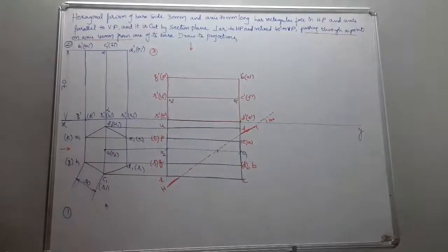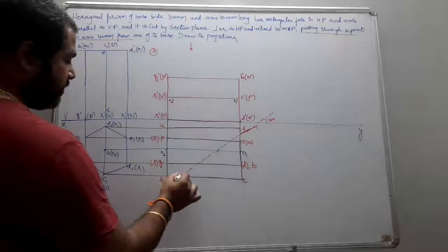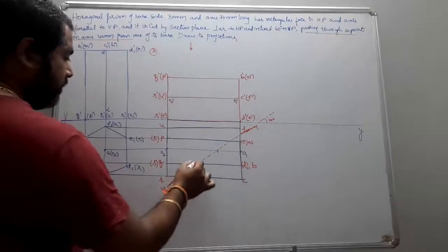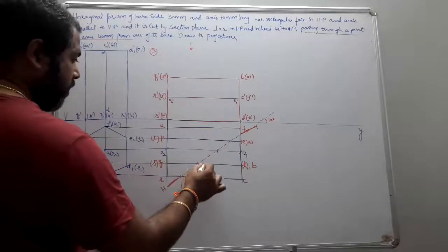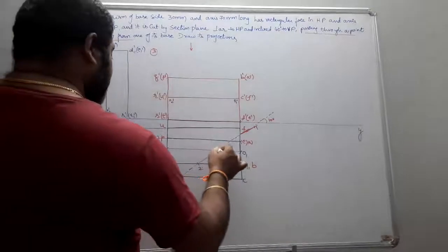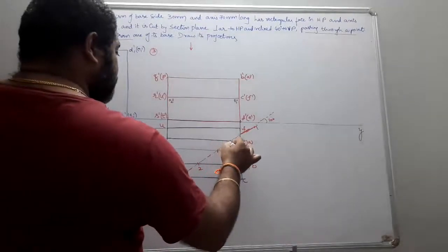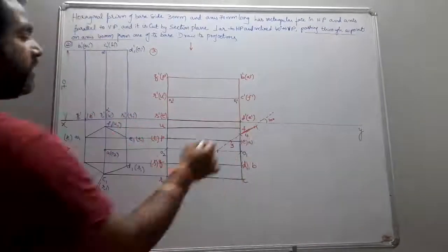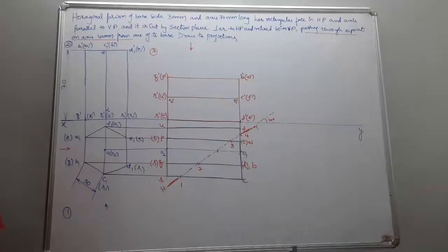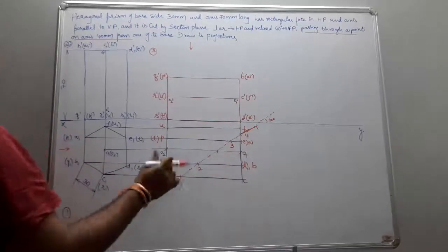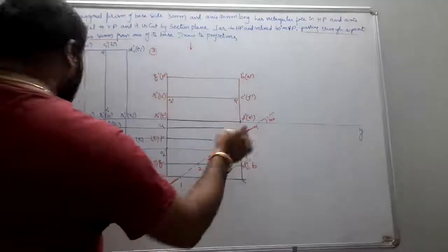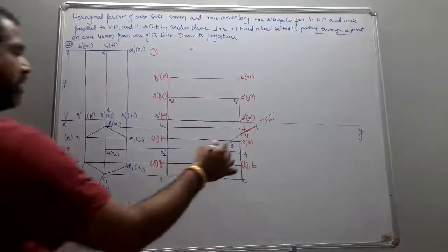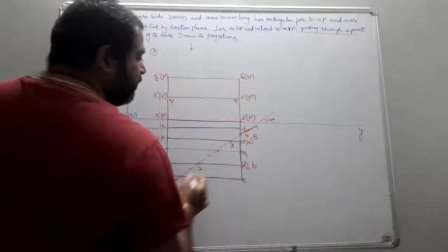Now mark the points where it is going to cut. Always start from the extreme left. So this becomes your point 1. Next this is point 2. Next the axis point, so this becomes 3. So here it is 4. AF is going to be the base. It cuts the base, so you obtain 2 points. When I start from there, I just get another point, point 5.